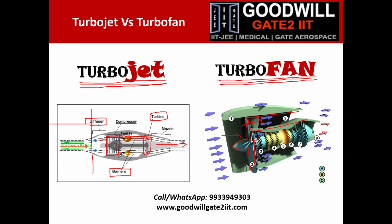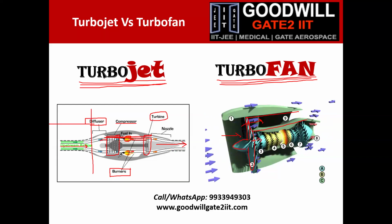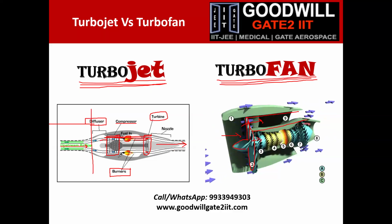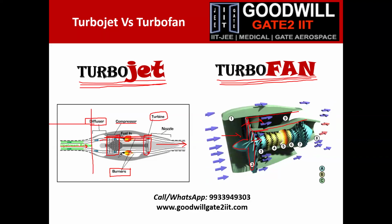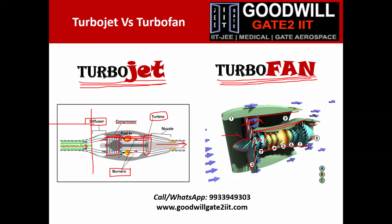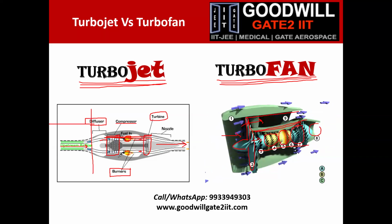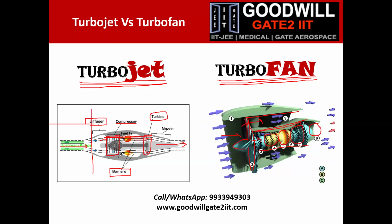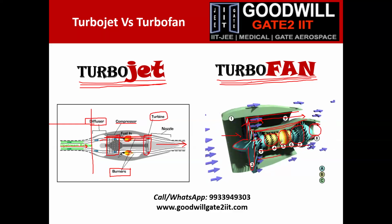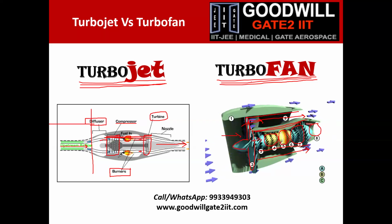Now this core engine is very similar to a turbojet. So what you have basically done is taken a turbojet engine and installed ahead of it a big fan, which is also known as a low pressure compressor. Inside this hot core engine, you will again see compressors, a combustion chamber, certain turbines, and then a nozzle. So it looks very similar to a turbojet. The only difference between turbojet and turbofan is this bypass duct, through which cold air passes. And this is where the major difference between the two engines lies.